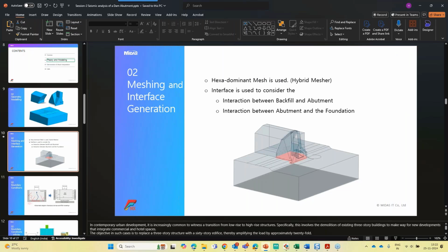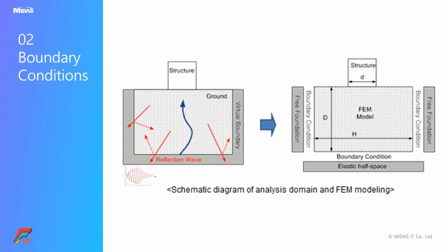So then next comes the boundary conditions. So the boundary conditions here are for both static analysis as well as the seismic analysis. So firstly, let's consider static boundary conditions for the seismic analysis. Whenever you have the static boundary conditions like a roller or fixed supports, in that case, whatever wave is going through the medium will hit the boundaries and reflect back, and thereby there will be very huge amplification happening onto the structure. That means the forces acting on the structure will be very high.